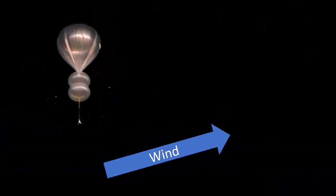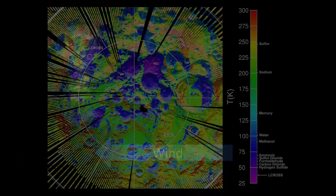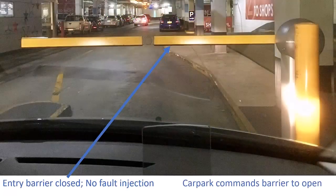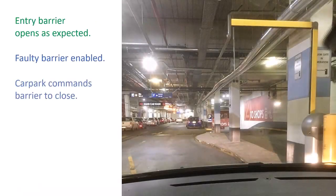Test bench models can give you the ability to control the environment in which your test models are operating. For example, you might want to test over the full range of a sensor's values, which may be virtually impossible with the real sensor. Modeled in a test bench, you can readily emulate the faulty behavior of sensors and actuators, enabling you to test and verify recovery paths within your application. During development of our balloon autopilot, a model test bench enabled us to fully test the behaviors of the autopilot independently of the test flight vehicle, which was being developed in parallel with the software effort.